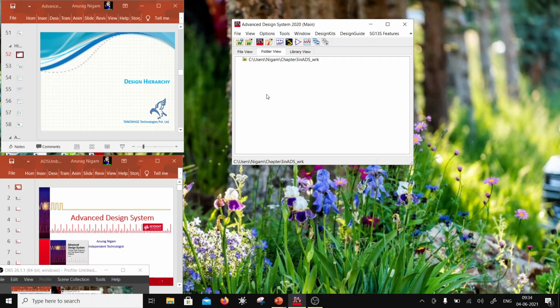Now the advantage of doing this is that it is going to be used for what is known as stability analysis. So you'll be able to do a Bode plot, and you'll be able to establish a phase margin. So this is going to be used mostly in analog circuit designs. So AC simulations are used for that.